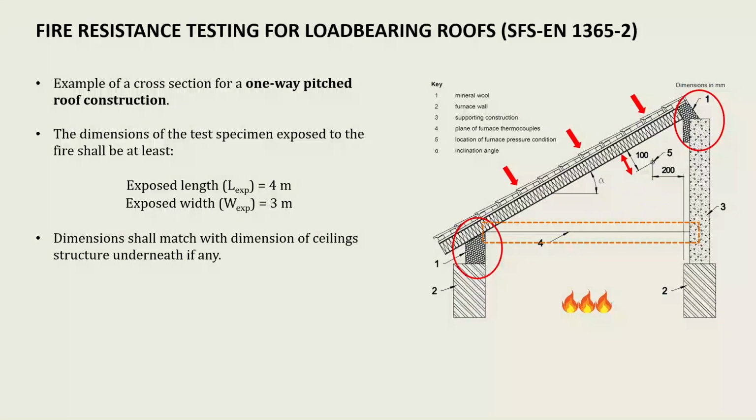Deflection is measured at midspan or alternatively at the point where maximum deflection occurs. It's typically on the top surface. Finally, the testing process for load-bearing roofs and the evaluation of performance follow the same criteria as those discussed in previous tests.